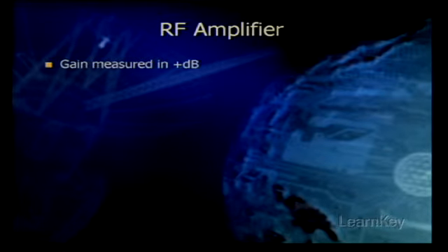Most radio frequency amplifiers that are used with wireless LANs are powered using DC voltage that's fed right onto the radio frequency cable with a DC injector near the radio frequency signal source, such as the access point or bridge. Most of the time when you plug your antenna directly into your access point, you won't have to worry at all about a radio frequency amplifier. But if that cable length should grow to a certain point, radio frequency amplifiers are definitely important.